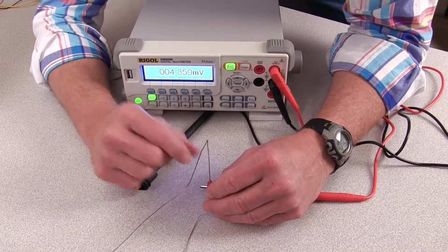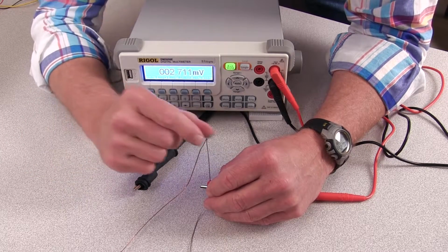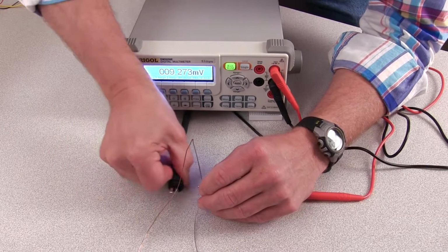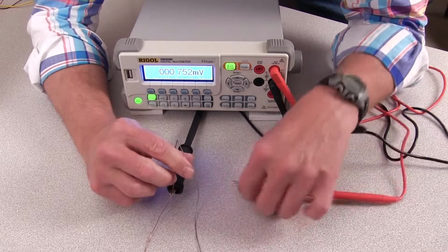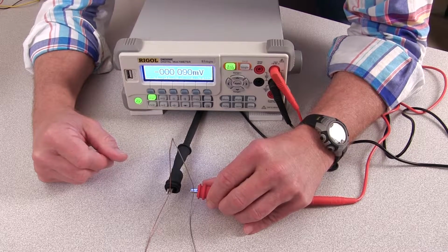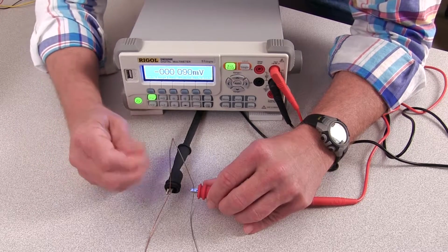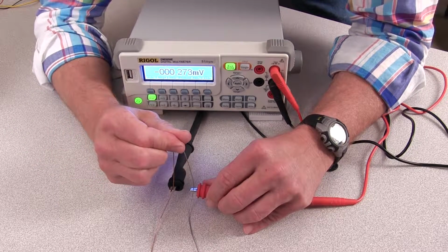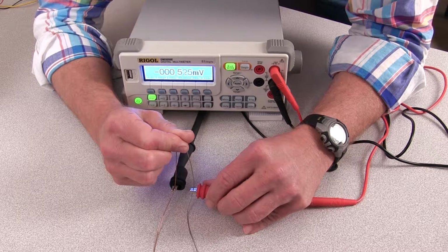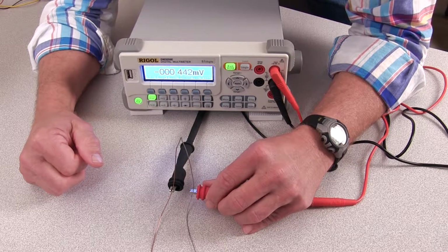This is a thermocouple. All it is is 2 different wires made out of different metals that have been joined here. If I change the temperature of this junction between these 2 metals, I should get a voltage out of it. So let me connect my DMM to measure the voltage across this terminal. I get about minus 0.097 millivolts at room temperature. If I warm this up by gripping it between my fingers, I get up to about a half a millivolt. I do get a temperature change out of this by warming it up. It's just not a very big change.